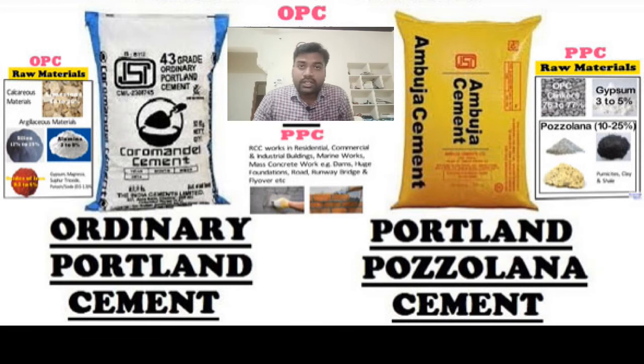But for the long run, for the structure, PPC is best. In my point of view, PPC is best, because the curing duration will be more, but it covers entire voids which you are going to get in the structure. That is the beauty of PPC.